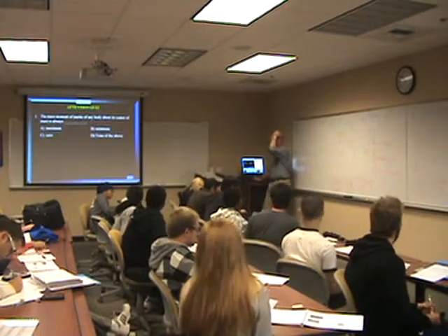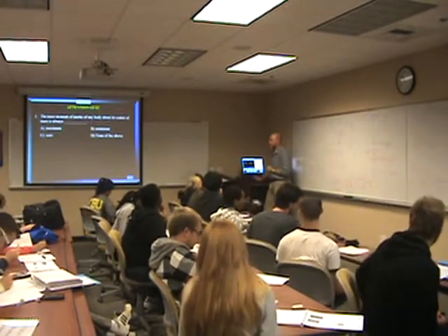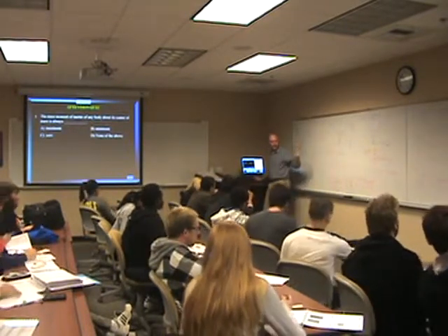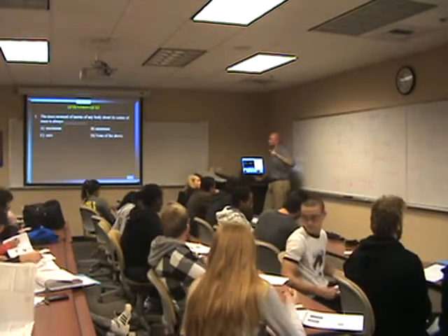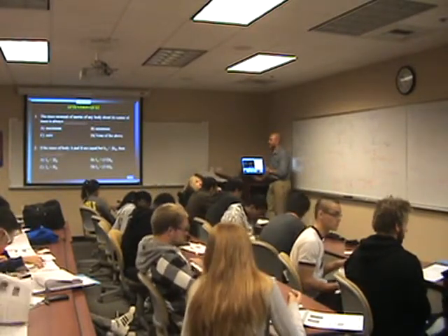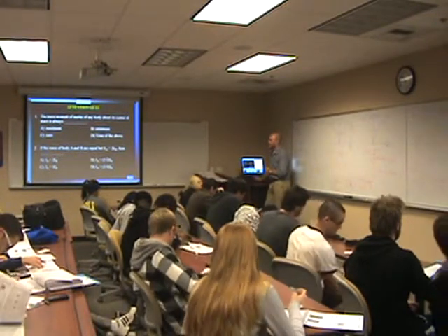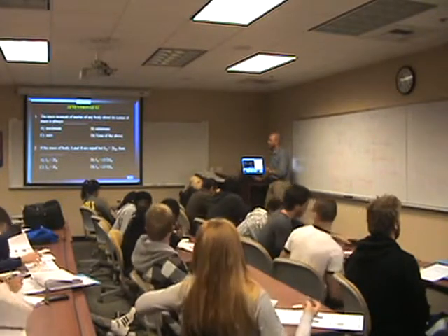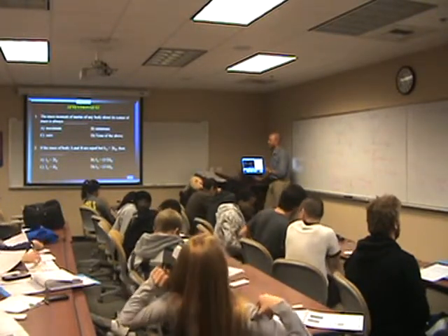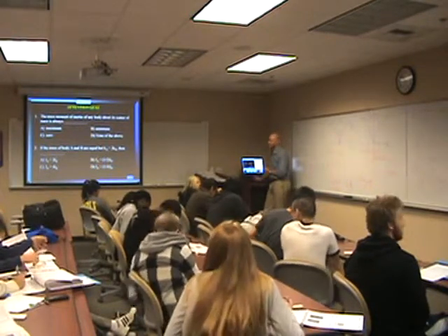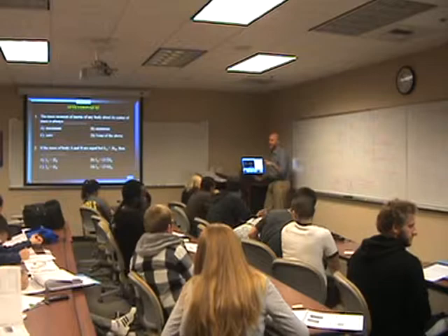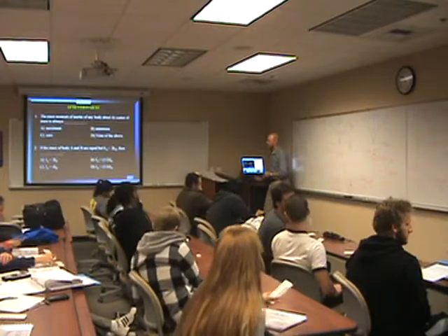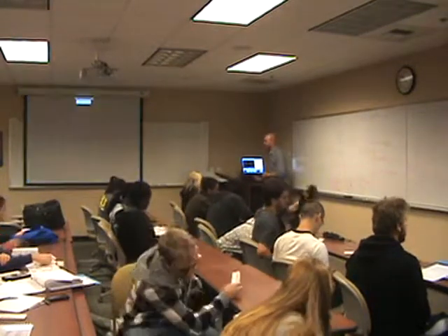Okay. Mass moment of inertia of any body about the center of mass is always minimum, because it's the center of gravity term plus m r squared, and so it's minimum about its center. And if Ka is 2 Kb, then Ia equals 4 Ib, because it's m k squared. So C is the right answer. That's it? Okay, got it.